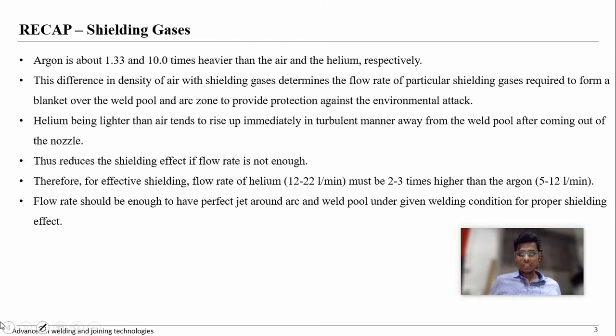Since helium is lighter than air, its density is less, so it tends to rise up in a turbulent way after coming out of the nozzle, away from the weld pool. Once it moves away from the weld pool, we need to supply more helium shielding gas.